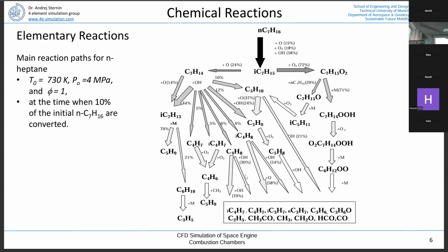So meaning that we quench, that we try to go very fast to the lean reaction and inject a large amount of cold air so that we lower the temperature, and go fuel rich in a very fast way, in order to avoid a certain reaction path that would end up in a large amount of NOx.